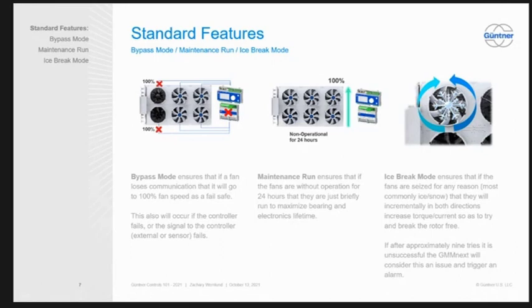So this right here is the number one service call I get. I'll get a guy in the field calling me, saying, "Hey, listen, the fan is working, but it's not responding. It's only spinning at 100%." To which I'll say, "Check the wiring. Is there something wrong with the wiring? Is there a loose wire?" And sometimes a loose wire will bring it back, and it'll start spinning again.